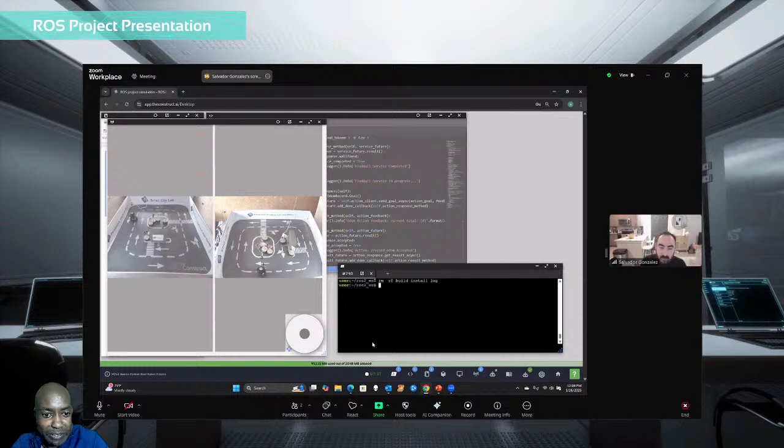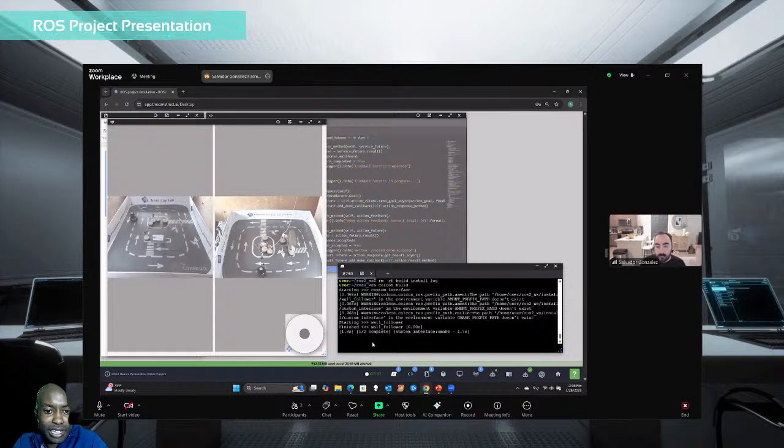And then you can have some pretty big control commands come in, and then that has some error. So it's very important to handle that swap from positive 180 to negative 180, something like that, in the laser scan readings.